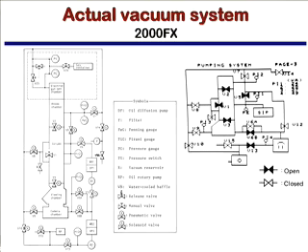You usually vent with nitrogen instead of air because it's a bit cleaner. Air has water. If you pump in nitrogen first, that absorbs to the walls and is easier to pump down after that. But what I did is just accidentally initiate that cycle. And so I said, oh, wait, the beam's gone. And then you look and you realize that's what you've done.